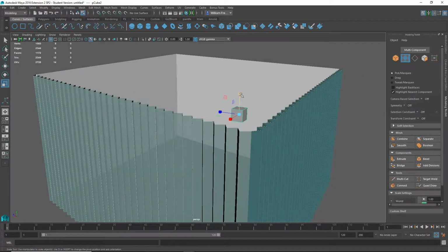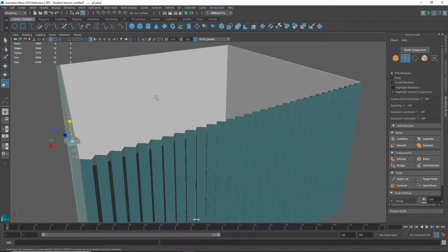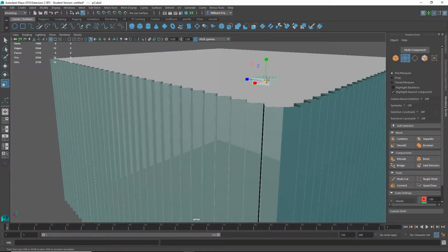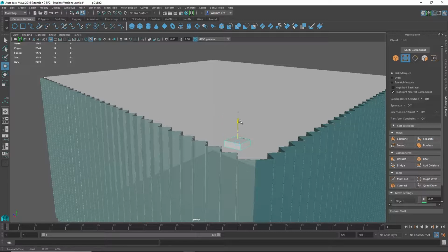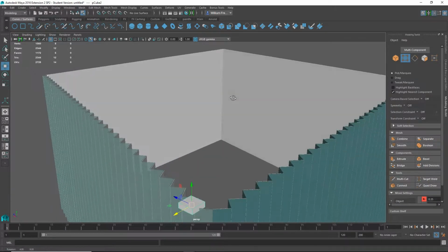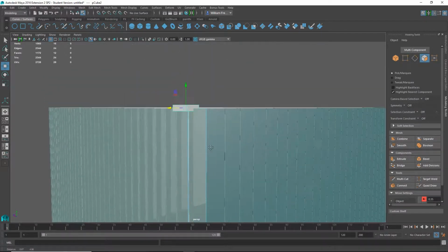We'll flatten that out. I'm going to go ahead and assign that opaque material to it instead of making a different one. The idea is this opaque would sort of be like wall paint color, I guess, like a white wall. Alright, so now I can drag this face. Whoops, selected the fin accidentally.